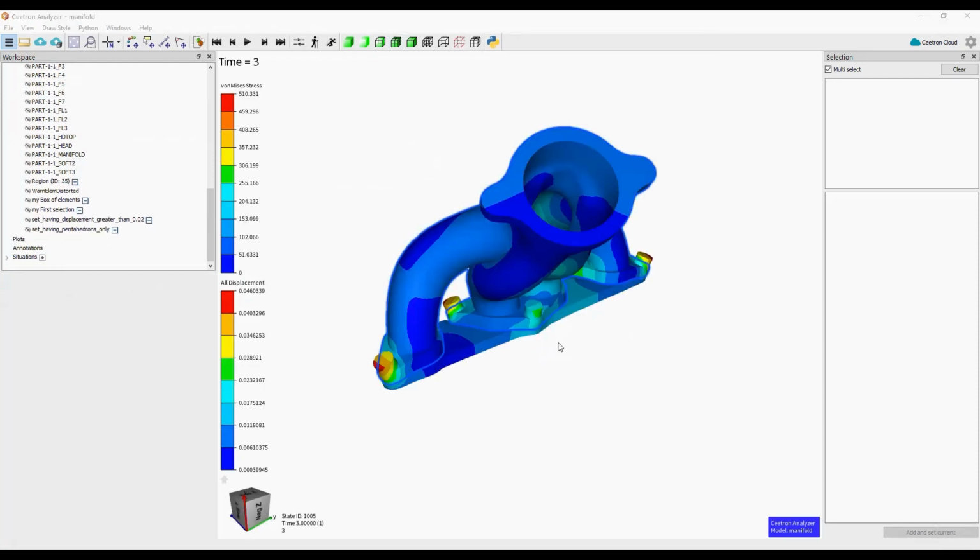This video will show you how to add a history plot to your view. A history plot shows the evolution of a result at a fixed location when the model state changes. These plots are mostly used when studying a transient, time-dependent model.